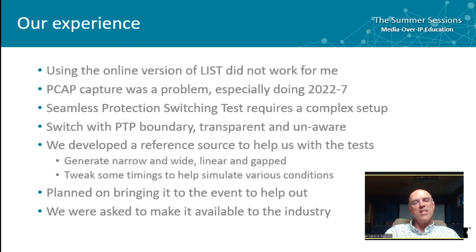Seamless protection switching tests require a bit of a complex setup, so that was a bit tricky. We were lucky because we had the same device that they used during the testing, so we were able to do those tests. But you may have to be imaginative to be able to do that part of the test. Definitely a switch capable of doing boundary, transparent, and unaware was useful for us to do some of the tests. The boundary was for the failover test, and the unaware and transparent were useful for other tests.